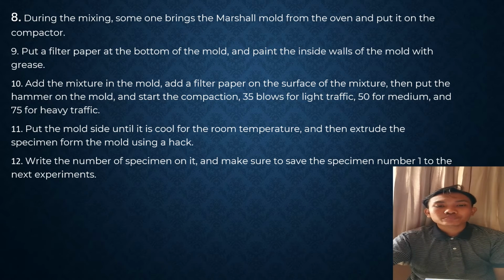Number 11, leave the mold aside until it cools to room temperature, and then extrude the specimen from the mold using a jack. And the last, write the number on the specimen and make sure to save specimen number 1 for the next experiment.